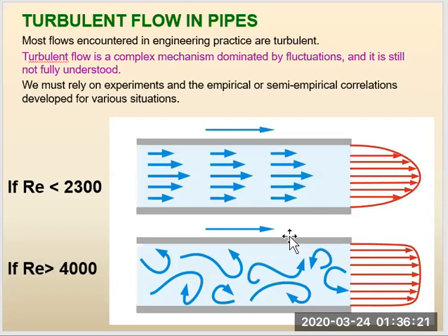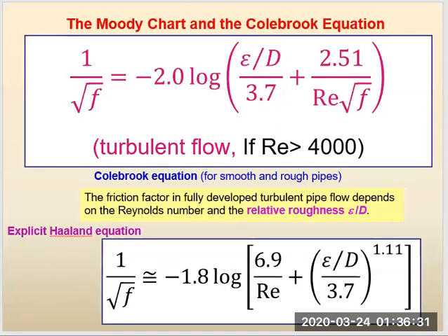As a result, turbulent flow is associated with much higher values of friction factor. So friction is larger in turbulent flow. If you have turbulent flow in a circular pipe, we cannot use the equation that we had for Darcy friction factor in laminar flow, that was 64 over Reynolds number. Here, our equation is different. It's a little bit more complicated to calculate.